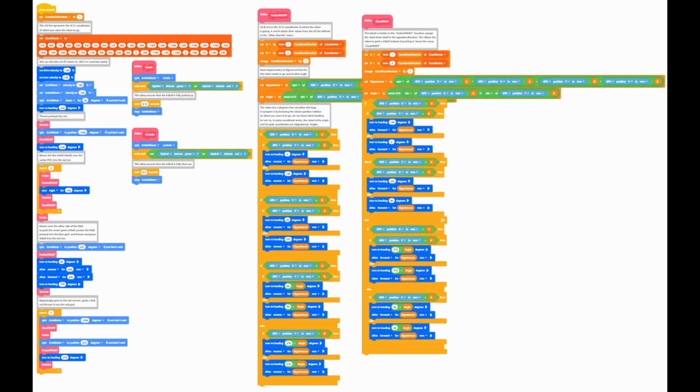The final function is claw front, which acts similarly to pusher front except with 2 differences. Firstly, the robot needs to turn 180 degrees extra to face the opposite direction, and secondly, it needs to move forward instead of backwards to move the same perceived direction. Now that the code is understood, the code can be seen in action.